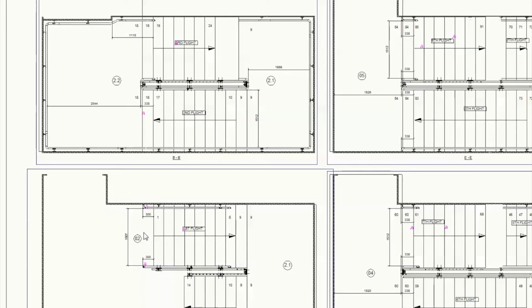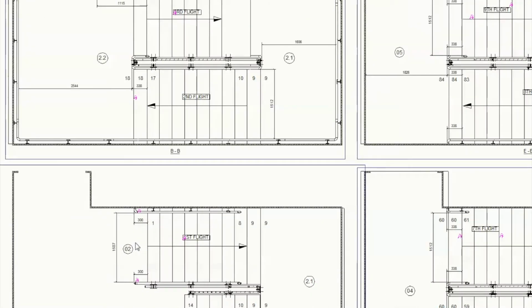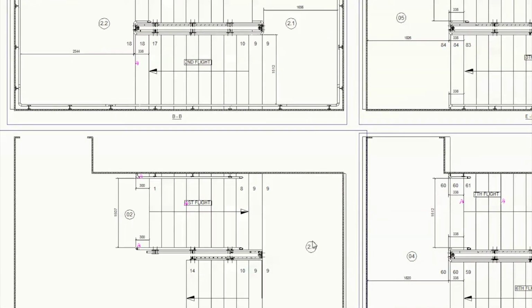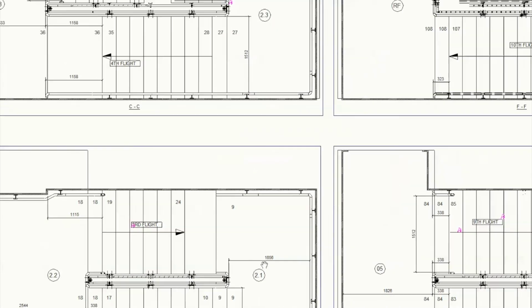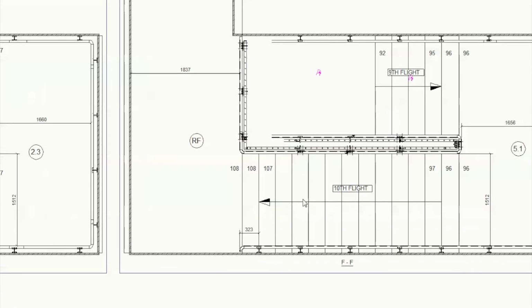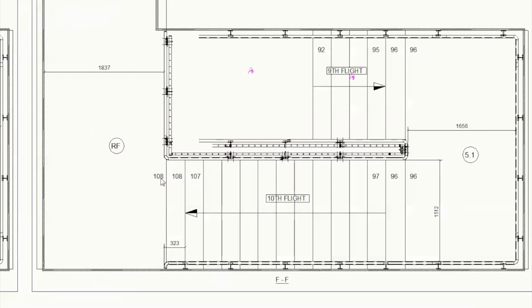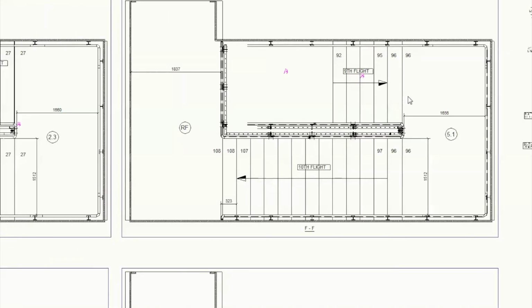So these plan views are a lot easier to follow than a lot of the architect's drawings that I get, because it shows the floor level, the mid landing level. I put a number on for the stairs. I don't number every step, it's ridiculous. So just number 1, right, that's your top step. Because of the way that I've modelled it, it looks like you've got an extra step in here. So I repeat the landing level number and just do all that the way through until you get to the top floor. 108, 108, 96, 96, 96, 96. And that should be quite easy to follow.